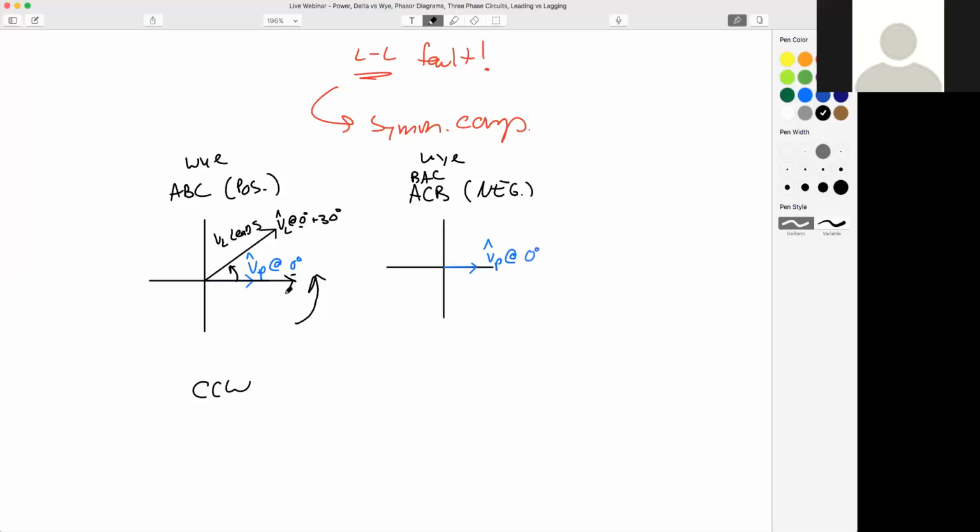But since we're looking at it when our phase is at 0, he's going to be leading. And ABC, it rotates negatively, but typically when we draw it on a phasor diagram, we still assume the same rotation angle, but we just draw the relationships backwards. So we would have it like this. So now our VL would be at 0 minus 30 degrees. Does everyone see that? Keenan said 30 degree lag. Exactly. Now VL is going to lag.